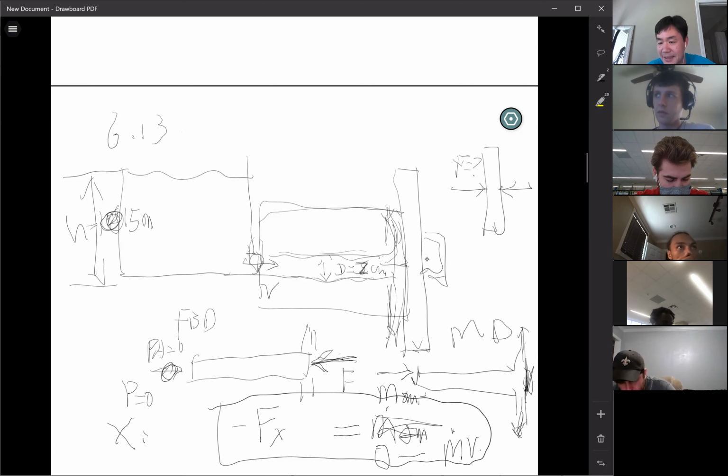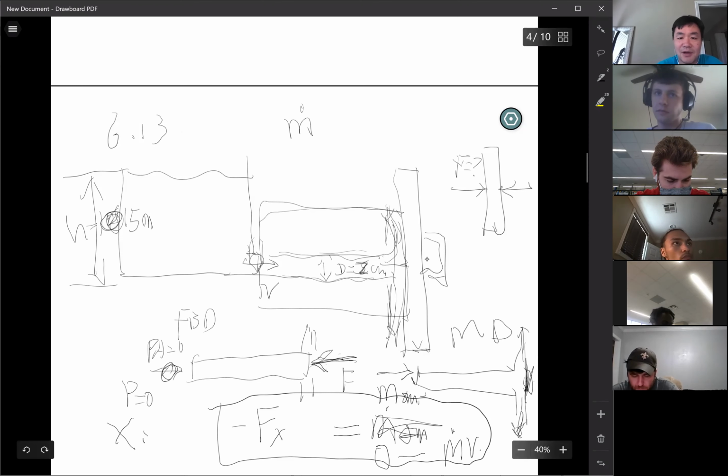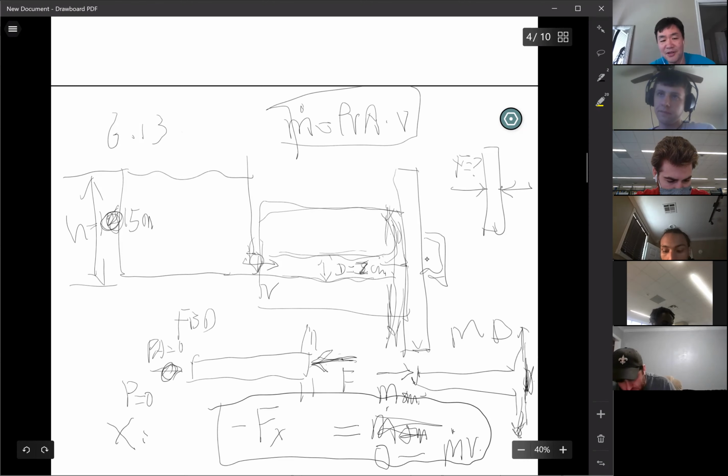Okay, that makes sense? So in the x direction, the equation will be extremely simple: one force term and one momentum term. Be careful, momentum out minus momentum in. Momentum out is 0 and the momentum in is positive. So this is 0 minus m dot v. Can you calculate the m dot v? This is a uniform velocity problem. m dot is equal to rho V A, times V. Basically, that's it. Velocity you can calculate from the Bernoulli equation, right?